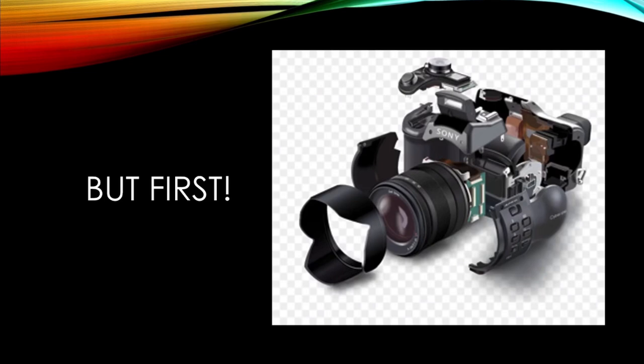The DSLR mirrored camera works by light entering the camera lens and reflecting off of a mirror inside the body that the photographer then sees in the viewfinder. They then take the picture, which means that the mirror swings out of the way and light hits the digital image sensor. This information the sensor receives then gets sent to an SD card ready for you to view, edit, and print. A mirrorless, on the other hand, is exactly that. There is no mirror reflecting, and thus the light hits the sensor directly.